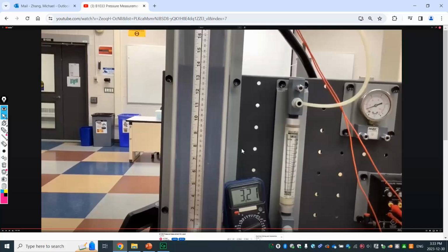That's basically the process of calibration. You cannot only look at either end. You have to take care of the trend, because at the end of the lab, I need you to show me that if the water level drops to the middle of the range, we should get 2.5 volt. That way we get an almost linear output.